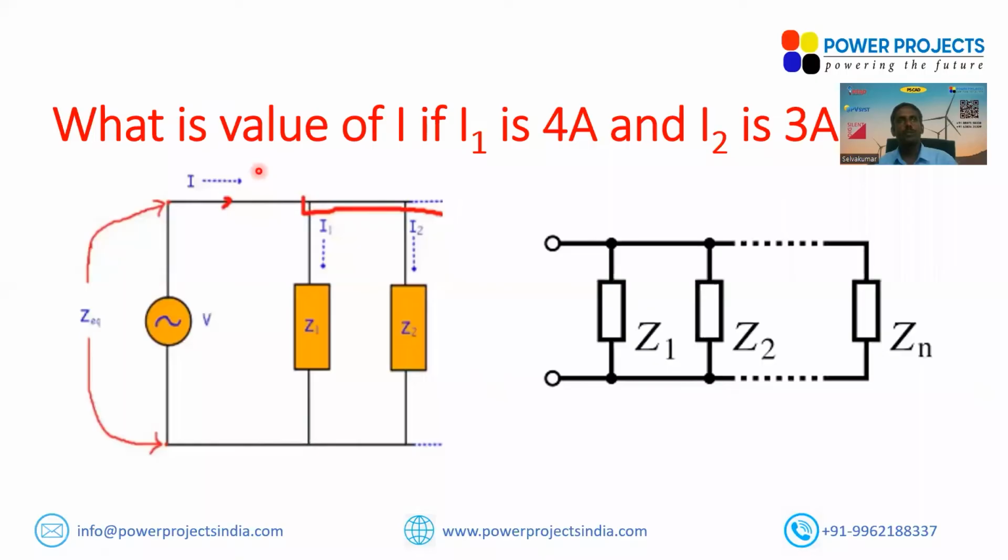Because most of the time, when people are trying to size the transformer or a diesel generator, or manually validate the transformer or diesel generator sizing during motor starting, they have the base load and try to add the starting current of the motor to check the overload capability of the transformer or diesel generator. Exactly here this happens: the existing load is at a power factor close to 0.8 or 0.9, and the motor which is going to start, any idea what the approximate starting power factor of the motor could be? It can vary anywhere from 0.1, 0.12 to 0.25 or 0.3. It will be in the range of 0.2. It can vary from 0.1 to 0.3.